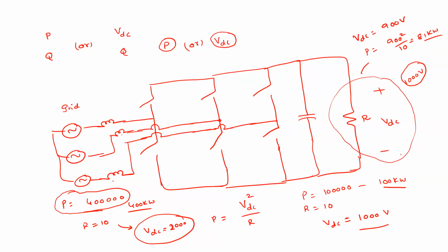And the thing is that either you can control the P or you can control the voltage across the DC side, right? So here there are numerous applications. For example, when you control the voltage across this DC side, if you are operating as a motor drive, then on the other side you have an inverter placed, right? So AC is converted to DC and DC is converted back to AC. Now this entire thing acts as a front-end converter. That is useful for a motor drive application.